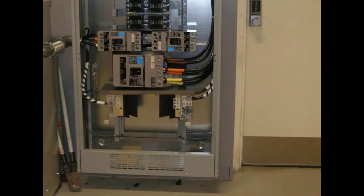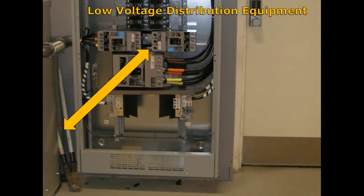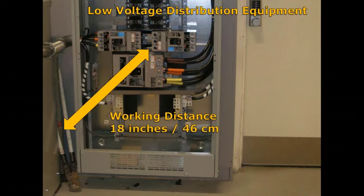The reason the working distance is so important is that when an incident energy is given from calculations, it's based on the person being a certain distance from the source of the arc, just like the definition says. For example, based on IEEE 1584 calculations, for low voltage distribution equipment such as panels, the working distance in the 1584 standard is 18 inches.